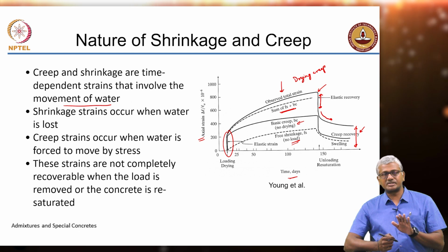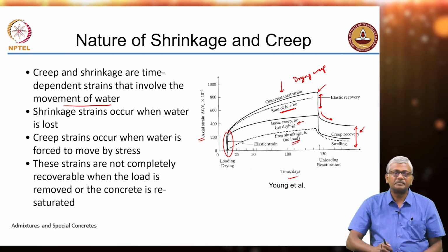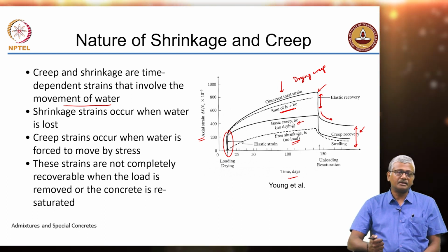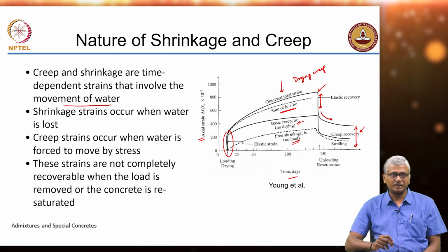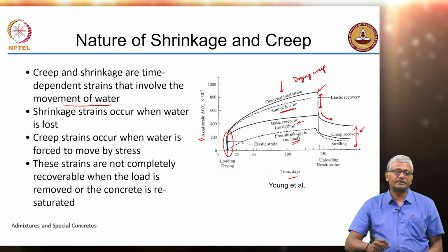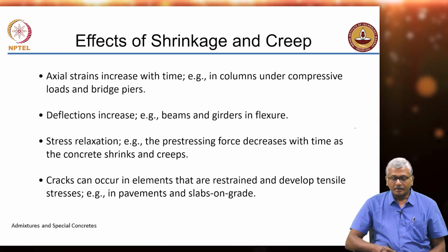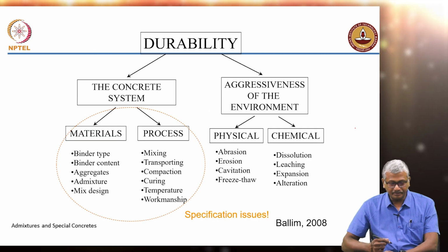When the steel loses stress and the concrete starts creeping, you will have a loss of pre-stress. So, in pre-stress members, creep and shrinkage are going to be extremely critical to analyze and design for, okay. And structures like tall columns in tall buildings are again going to be subjected to very high levels of creep and shrinkage. Right. So, again we talked about this already, so I am not going to discuss this again.